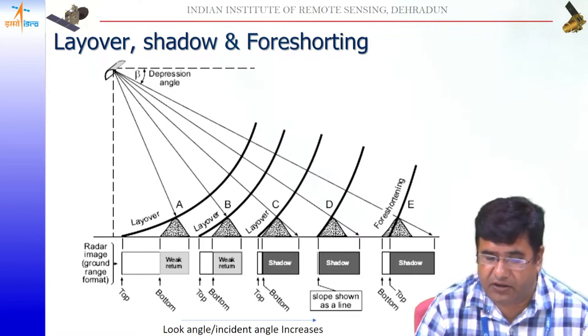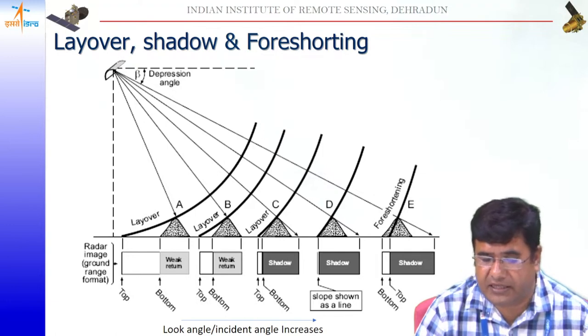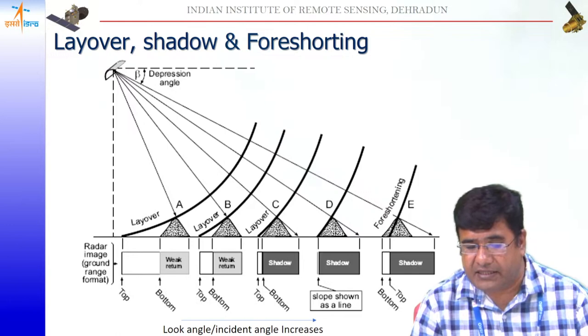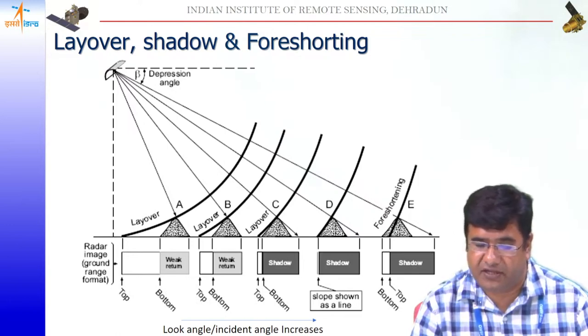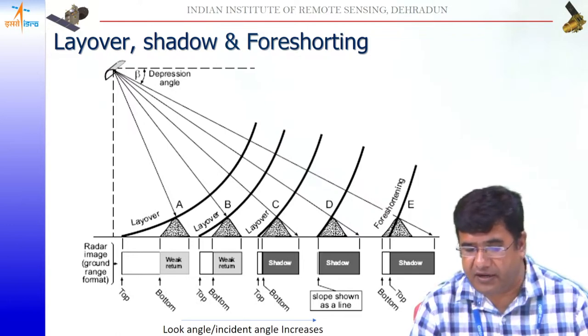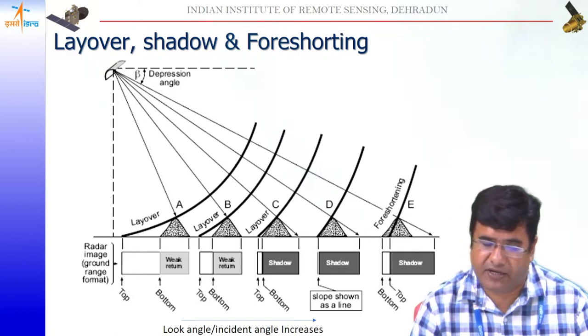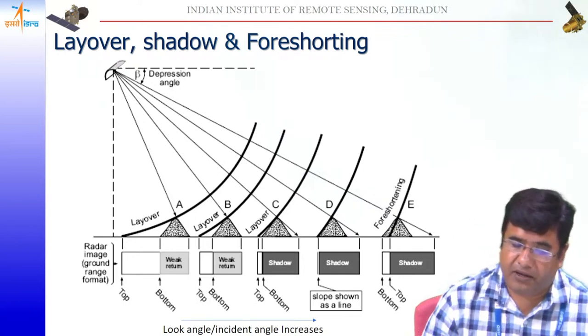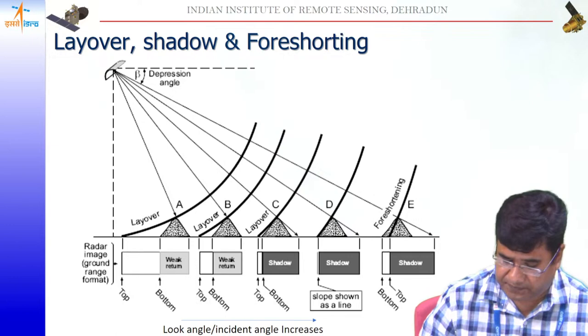So if your feature is not coming in properly in the SAR image, you have to adjust the look angle of the radar. You have to either increase or decrease the look angle to actually acquire the proper feature in a SAR image.